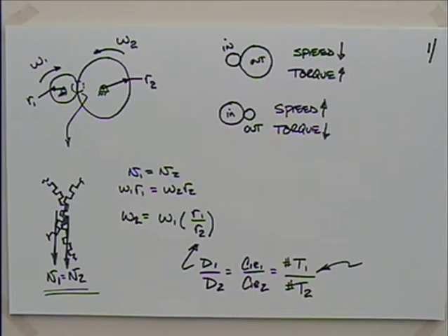And you'll have to do what they call matching the gears. If you look at a lot of the large trucks going down the highway, when they are switching gears, they're probably not using their clutch. They're actually matching the gear speeds as they go along. And that's why when you see them downshift, a lot of times they'll rev their engine a little bit as they downshift, because they're trying to match those gears.